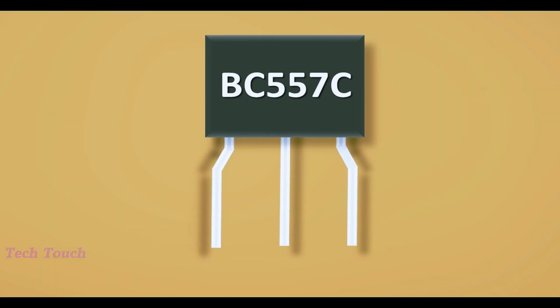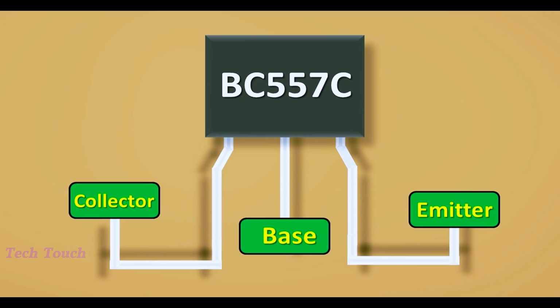Transistors basically have three terminals. These are called collector, base, and emitter, respectively. Current enters the emitter of the PNP transistor and exits through the collector. The flow of this current is controlled by the middle terminal, i.e., the base. It is worth mentioning that the BJT transistor is a current control transistor. That is, the transistor is controlled by giving or not giving the base current to the BJT transistor, or by giving less or more current. The base current IB controls the collector current IC.